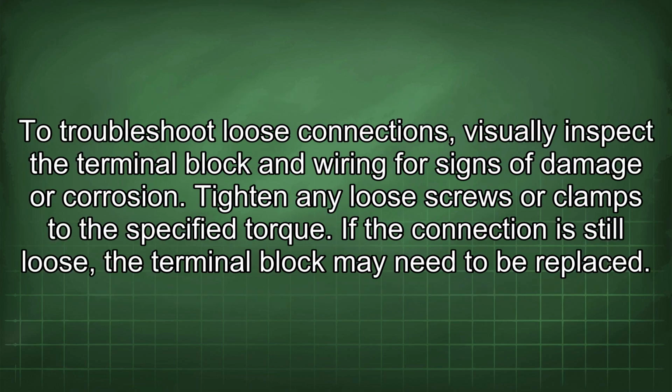To troubleshoot loose connections, visually inspect the terminal block and wiring for signs of damage or corrosion. Tighten any loose screws or clamps to the specified torque. If the connection is still loose, the terminal block may need to be replaced.